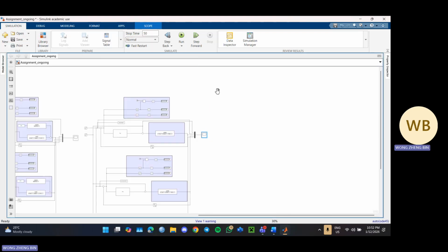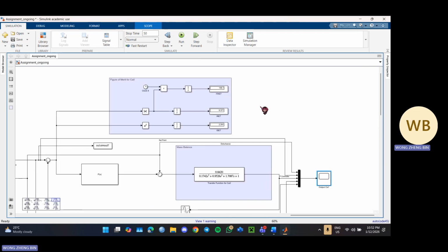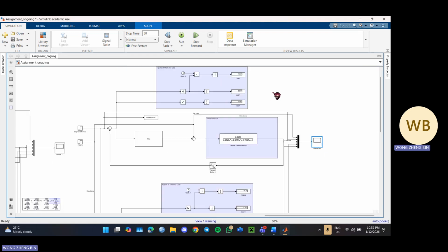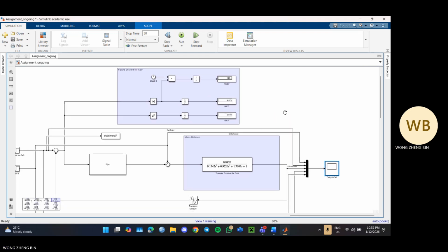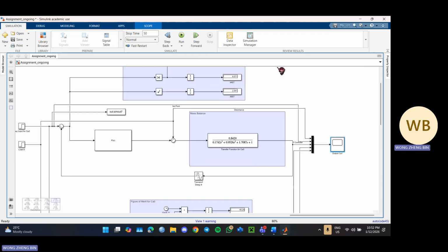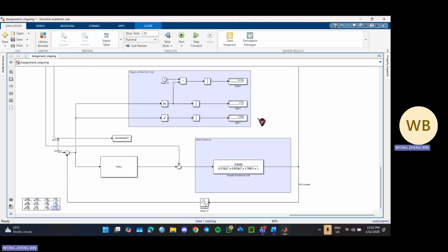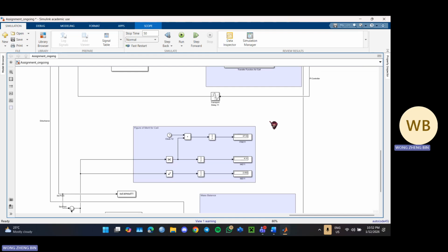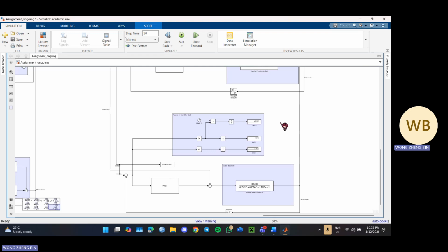So basically the same. When we added the load, the error becomes a bit higher than in the servo case. So basically this is the regulatory case. You can see the p-value, the error for P controller, error for PI controller, and error for PID controller. It's getting smaller if you increase the I and D inside the controller.